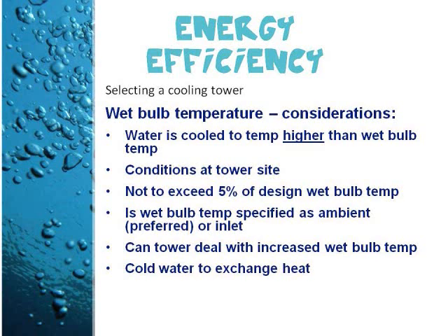The following should be considered when selecting a cooling tower based on the wet bulb temperature. Theoretically, a cooling tower will cool water to the entering wet bulb temperature. In practice, however, water is cooled to a temperature higher than the wet bulb temperature because heat needs to be rejected from the cooling tower.